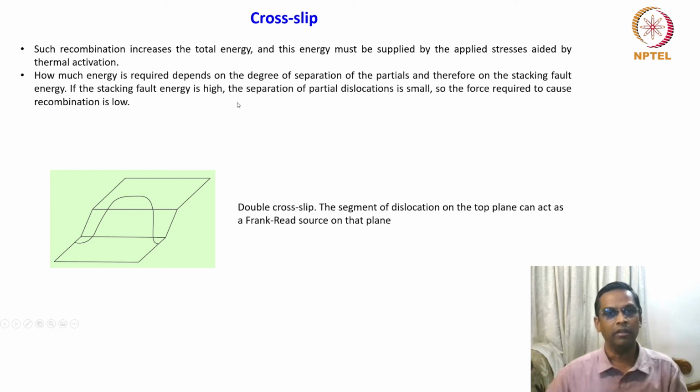Yesterday we started with the partial dislocation, and then I raised one question. The title I showed was partial dislocation in FCC crystal system, right? Then I raised the question, why not in a BCC crystal system? Then I mentioned it's not that partials are not there in BCC, but they have a very unstable configuration. Even if they exist and recombine, they exhibit a very unstable configuration.